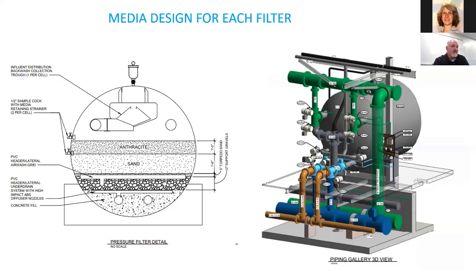Along with that, we draw what we call a water quality model sample, and we perform water quality tests, and those tests are monitored to be able to predict corrosion control, and that also goes into determining what blend of phosphate we use and the application rate.